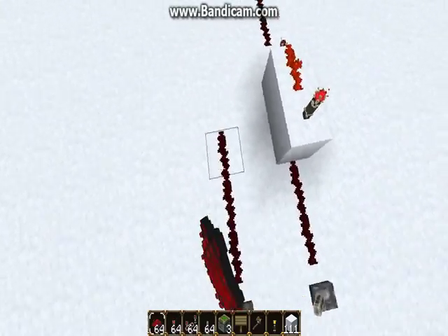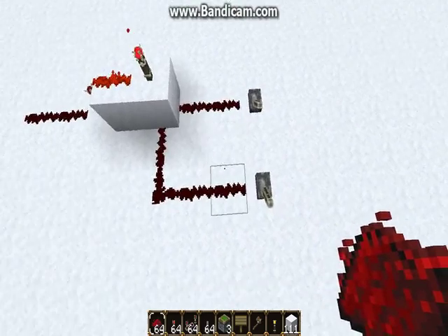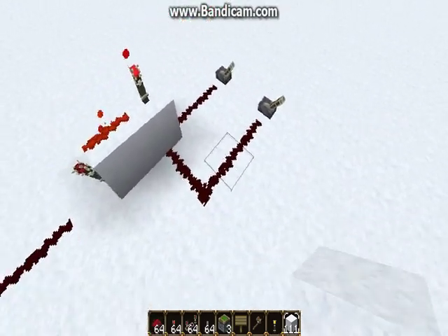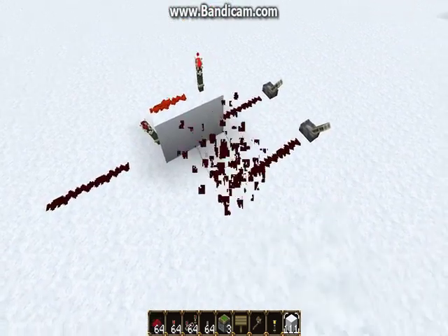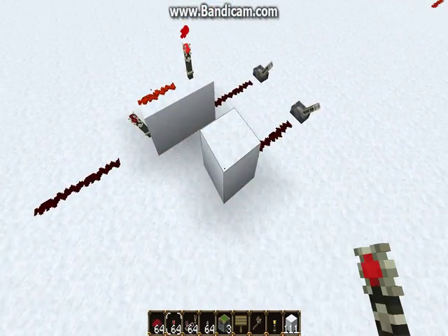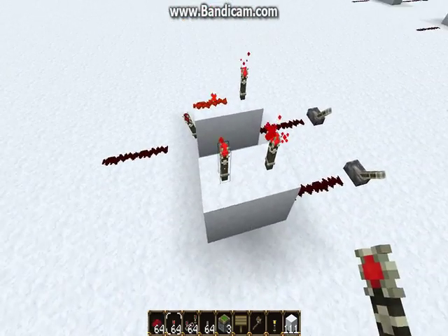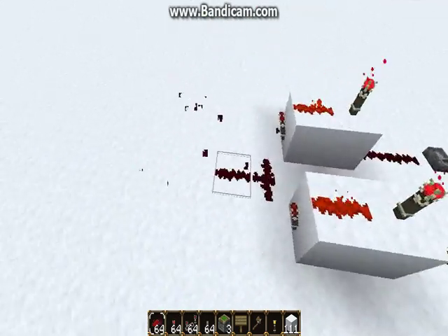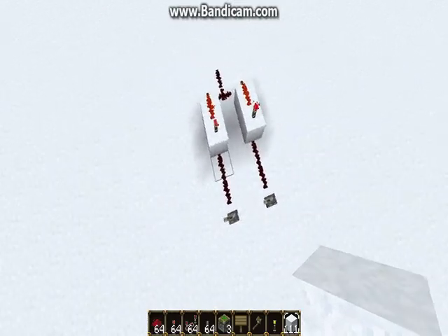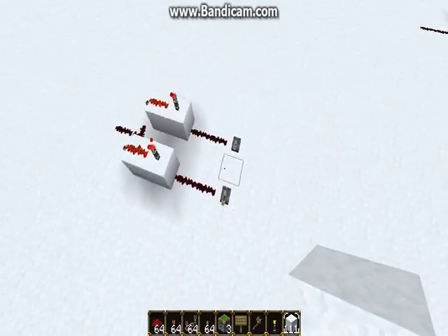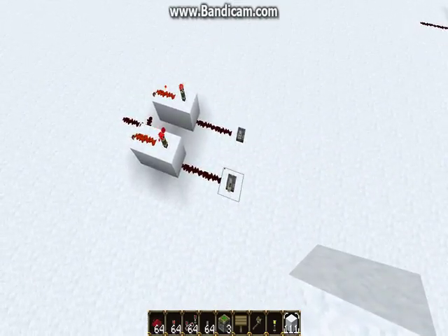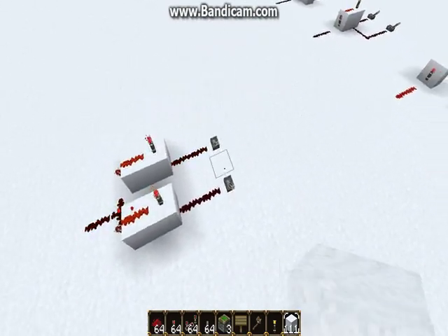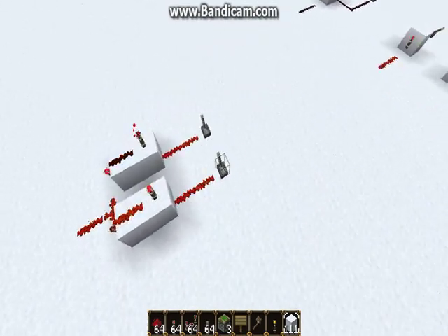And if I wanted to have a second input in here, that's not necessarily going to be the first input anymore. It could also be the second input. We need to keep the inverse of those separated. So I'm going to build a second OR gate and combine their outputs to create the function of the final XOR gate. So this works just like an OR gate. Flip 1, output, flip 2, output, flip both, output.